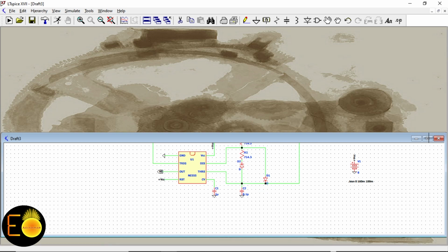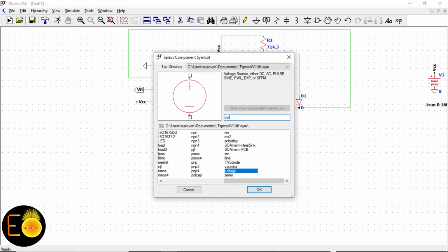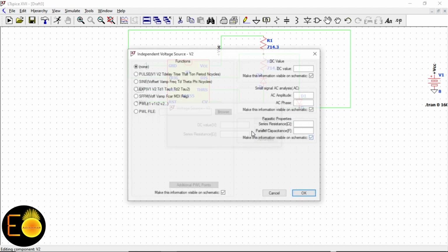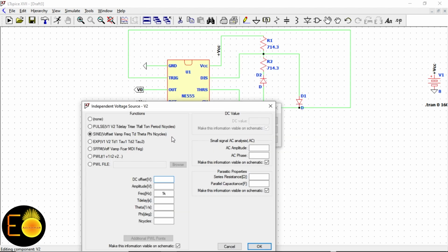Okay, now I'm confident enough to put the values of the voltage source, and as the frequency of the output is 10 kilohertz, now safely I can put a sinusoidal signal of frequency 1k. Now the amplitude, and one thing that you should be careful about, the DC value you have to put at the center of the maximum rail values available in the circuit. So maximum rail values are the 8 volt and 0 volt. So the center value of them is the 4 volt.